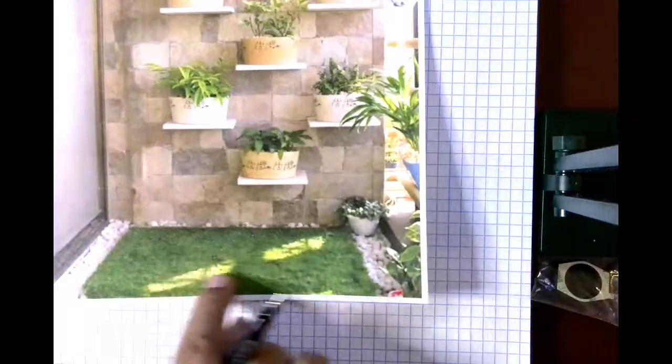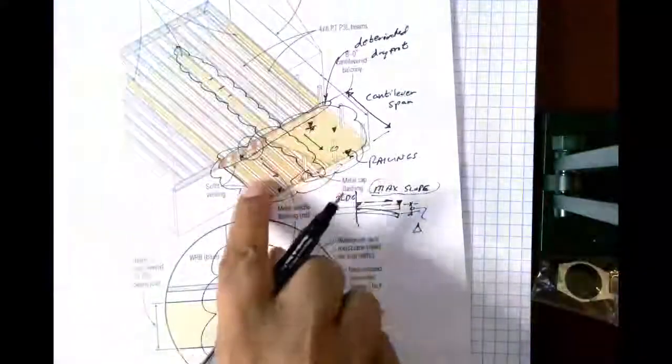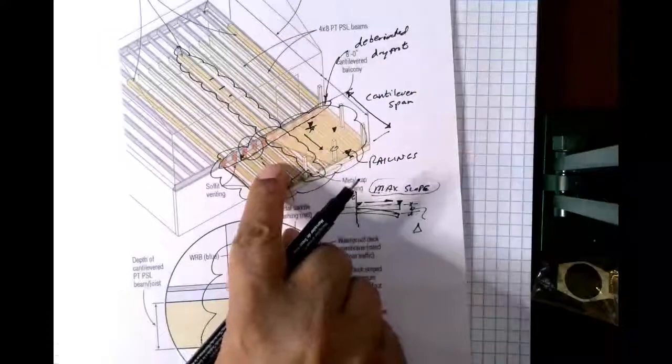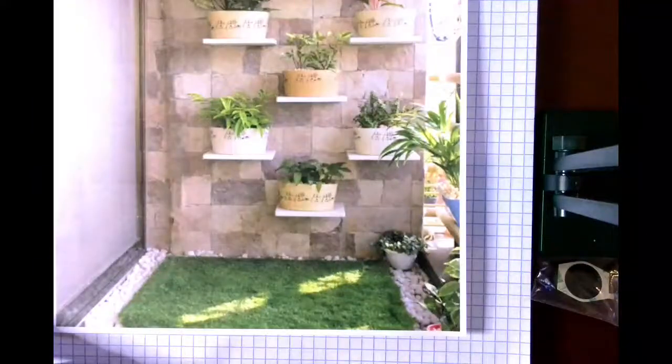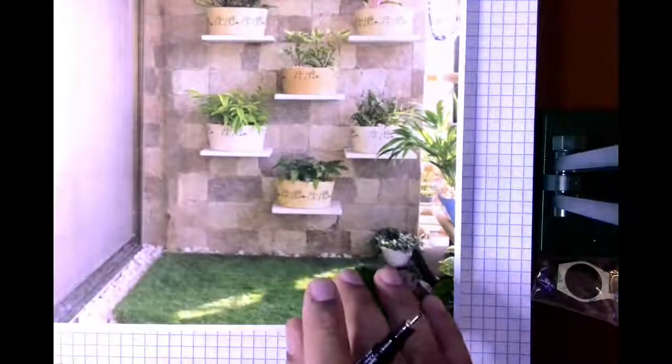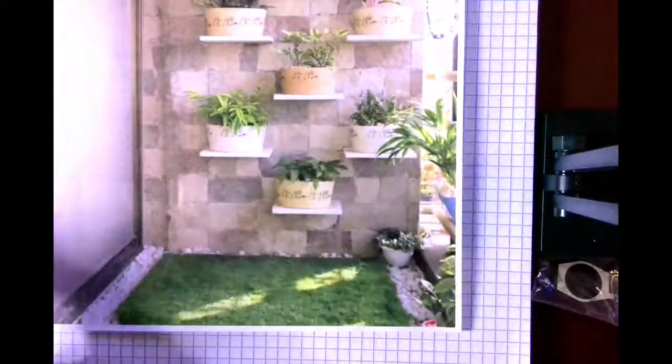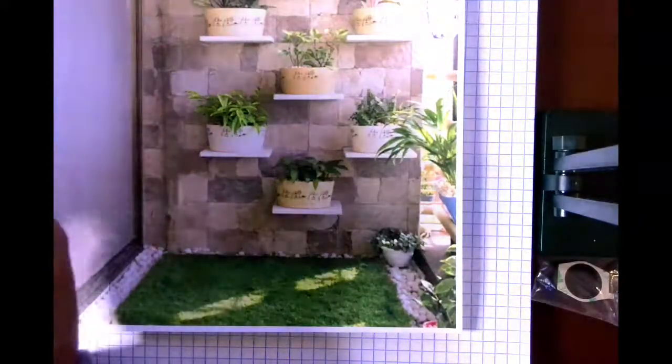So this water, where does it go? It's going to seep down through this system, and if this balcony doesn't have waterproofing, the water is going to cause dry rot. It's going to cause termites. So even though it looks beautiful, and yeah, I love it, it's not such a great idea. Unless you plan for it, which is put a waterproofing membrane in. Make sure your balcony is strong enough to handle that extra load, because otherwise you're going to get this condition.